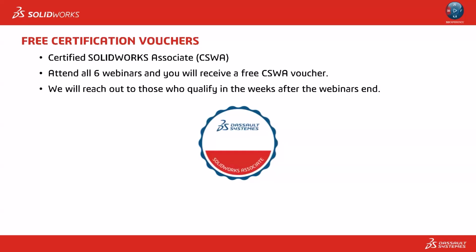But what that is, if you have two mates and they overlap, a mate, by the way, constrains any number of 6 degrees of freedom, right? You have rotational movement in three directions and translational movement in three directions. And you can define a mate to constrain 5 degrees of freedom, but if you also define another mate to constrain some of those same degrees of freedom, sometimes motion can give you some issues.